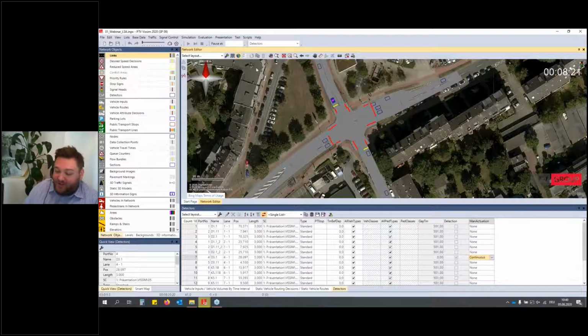One of the great advantages of our simulation software Vissim is that we can not only test our signal control in our test mode. I would stop the test mode for this moment. But we can also test it with real traffic volumes. In this case, we can check how our signal control would perform considering the given volumes.